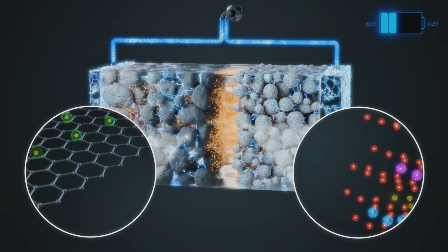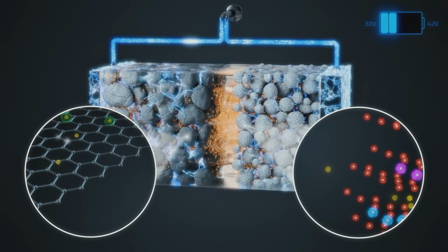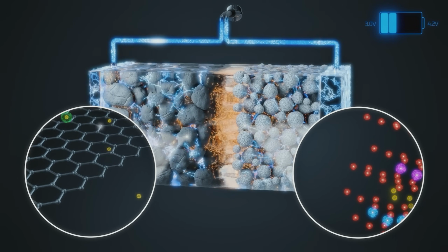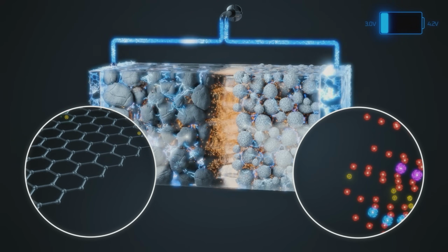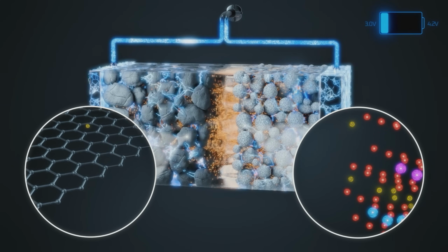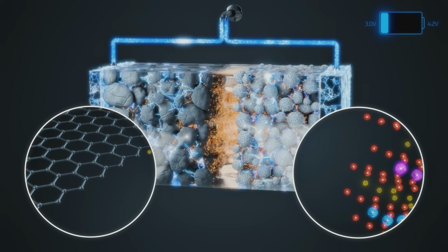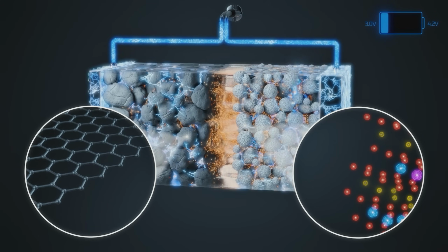And so, the method we use in the lab, the sort of gold standard method, if you like, to measure state of charge, is called Coulomb counting, which, again, I'm sure you and many listeners will have heard of. It is what it says on the tin. So basically, you count the number of electrons going through your external circuit, which sounds very complicated, but it just means you have a current sensor and you take the measurements of current instantaneously and you just add them up over time. Mathematically, we integrate the current.